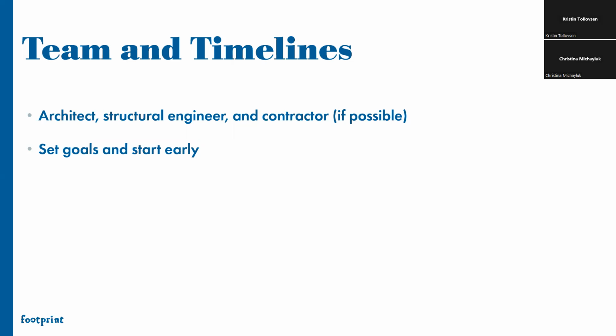When looking at zero carbon framework and LEED, they both talk about that global warming potential, but there are other impact categories that are available within the LEED rating system as well. And depending on what changes are made, there's always a potential that one of them could result in an increase. So it's important to know where you're standing with that and make those decisions early on, and bring in as many people as you can into the team.